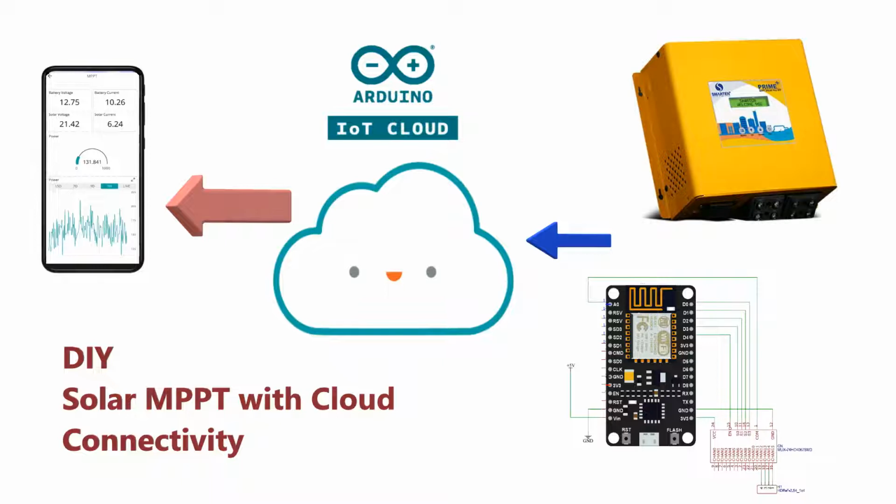The next idea was to have a separate sensor. For the voltage readings, we can have a voltage divider resistor network. Also for the current, we can have a current sensor, the ACS786, which is basically a Hall effect current sensor. I thought of using these for getting this information.